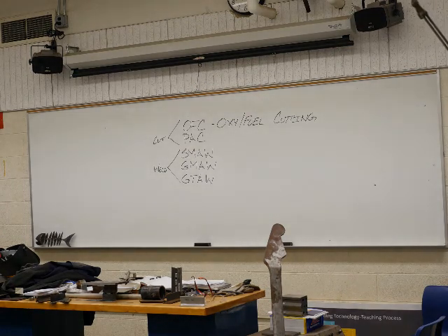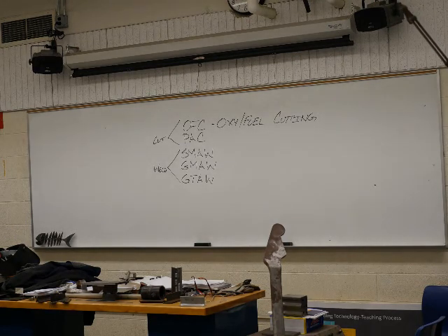Well, you don't do that. You're kind of just pushing it in. It'll open up a little hole. Okay. So you want to have a little bit of a gap. No, front side. You're always welding from the front side. Think of this being like the inside of the pipe. You can't weld the inside of the pipe. Okay. So that's how we weld it. We want the weld to go all the way through.